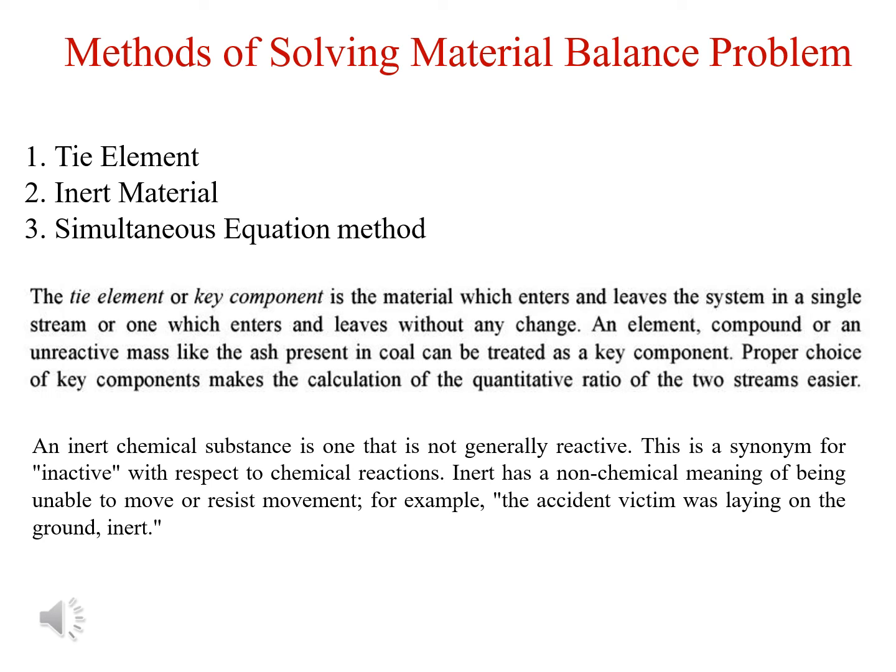In the second method, inert material approach, the substance present in a feed material will not generally be reactive, it is inert to the reaction, so inactive with respect to the chemical reaction. So during the combustion reaction some material will not react with the reaction, so based upon this inactive component we are deriving the material balance problem. So that is inert material approach.